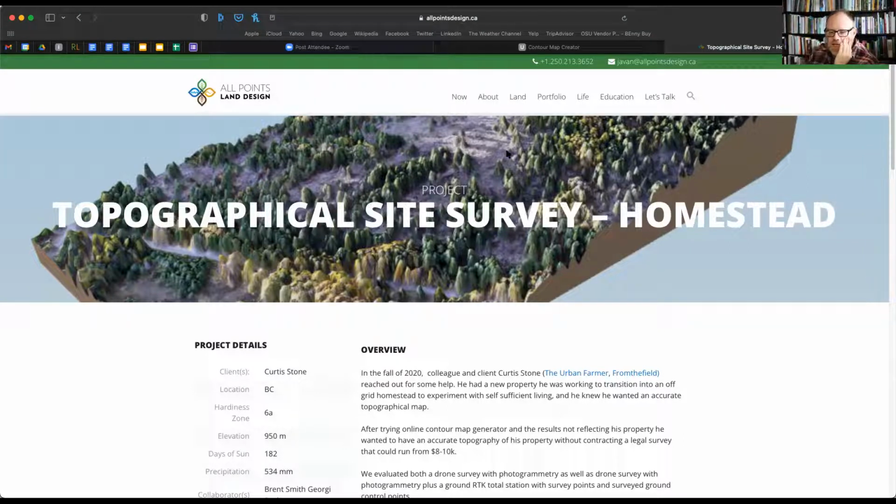And then I walked around and put on these little ground control points. These ground control points were me taking a spray can and making a square and filling in two sides of that square. Then in one of those squares, putting a number. So one of these was 1, and another one was a 2. And then we had a rover, which is a receiver that speaks to the RTK total station. Javin walked along with a little flag and we took the center of each of these ground control points. So we've got the ground control points and the real-time kinematic, and with this receiver we can walk through the forest and take points.